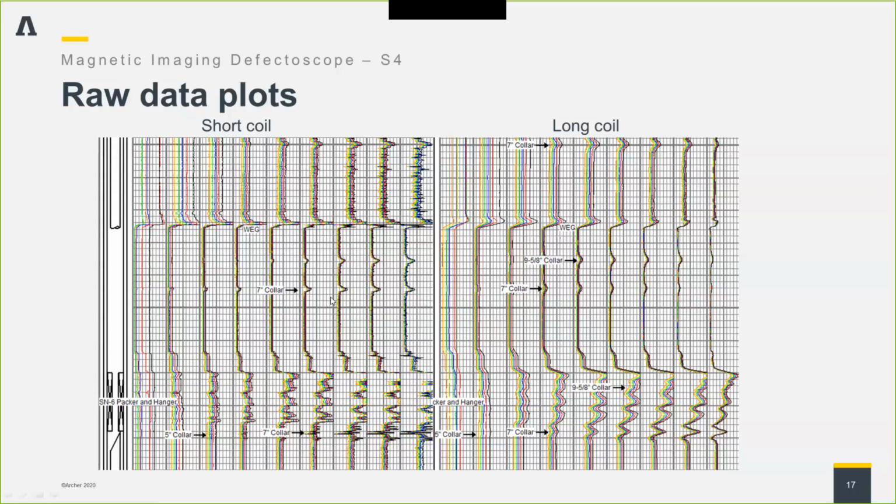And then we're going into the bottom here to a packer with a tubing hanger. This is into a 5-inch liner. Sorry, a liner hanger. So we can see as we come down through all the bits and pieces of the packer and then into the 5-inch collar. So that gives us a different baseline. So again, if we log one of these tools through a complex completion, we are able to go through and identify just from the raw data all of the individual completion items and use that for quality control, depth control, and to look for any immediate problems with gross features.